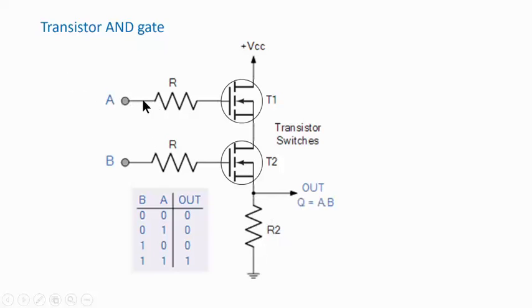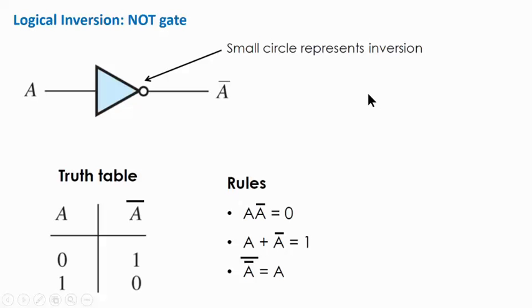If one of the gate voltages is zero, off, this will cut off one of the transistors, and they are in series, so the current through this transistor is zero, then the output will be low if one of the gate voltages is low. So in order to get the high output, both gate voltages should be on, as you can see, because they are in series.